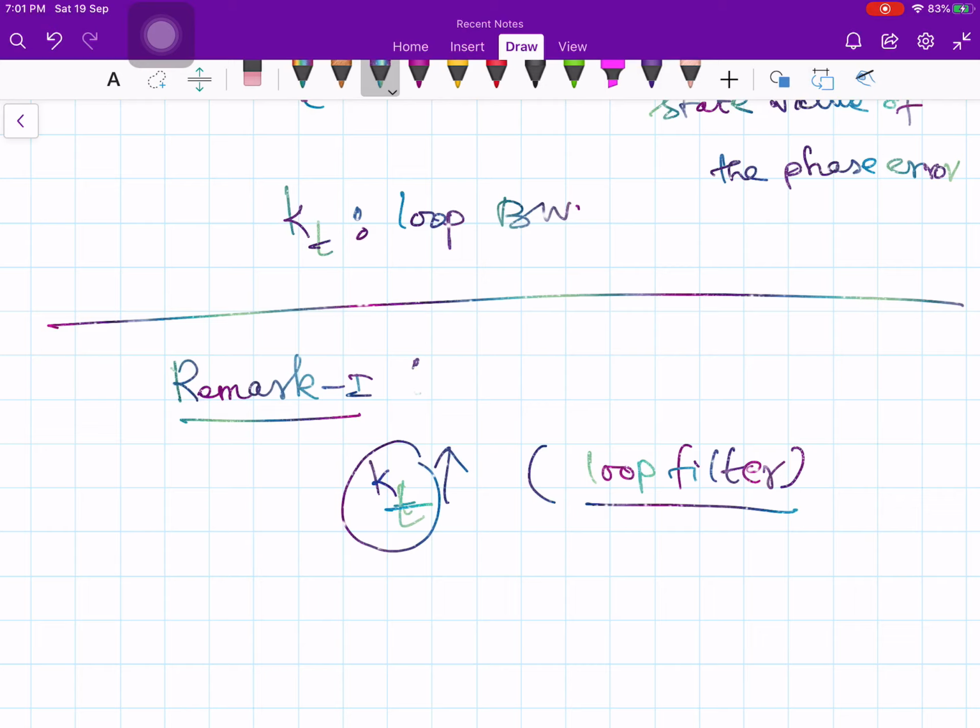So far the phase detector output, except for the multiplication by the loop gain, was directly going into the voltage controlled oscillator input. So it is very easy to relate through the integral or through the differential equation. The moment you add the additional filter in between your voltage controlled oscillator and your phase detector, there will be a problem, and that affects the entire description in terms of either differential equation or integral equation. So it just becomes a little more complicated.